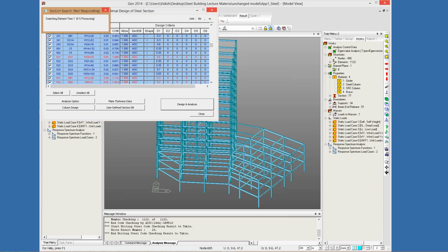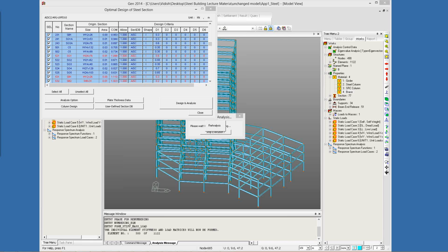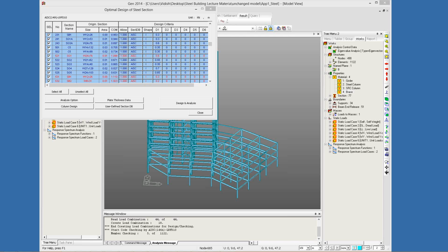position, redefined elements. And once you update them, if you find that they are useful, if you find that they are okay, you can just update those elements, and you can actually even see a comparison between the two to find out whether or not the weight is actually being reduced. So here you can see the reanalysis is being undertaken. And once more, Midas will do a member check. And once the member check is complete, it will give you a complete and full detail of all the changes that have been made and also of the comparison that was done.